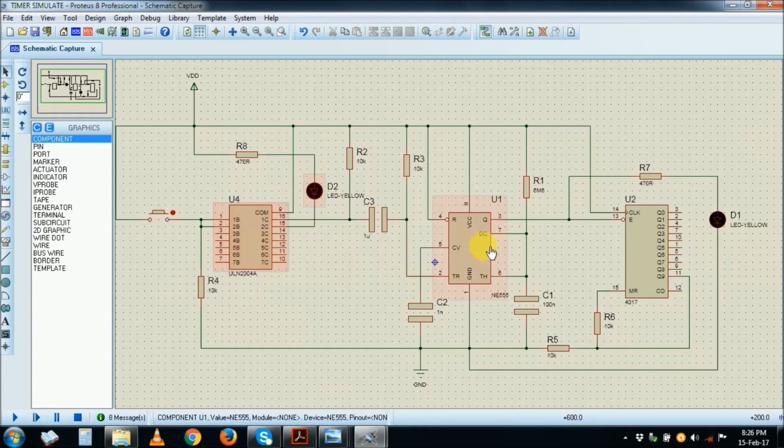You see that the timers themselves will actually step this clocking circuit by themselves. When we have an output from one of the timers, that output will actually be transferred back to the counter to step it to the next position, whether the timer that is stepping the counter is from within the same side or from the other side. You will see how I've constructed the circuit.